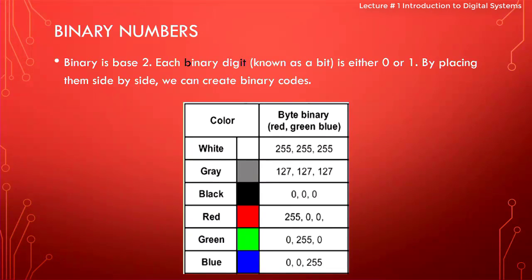Television sets, you see the resolution is improving. There are millions and millions of pixels on a screen. You can actually generate those pixels by digital logic, okay? And in most TVs, it is actually created using a certain bit number system for red, green, and blue. These are the primary colors, right? So this is the 8-bit system. For an 8-bit system, you can go from 0 to 255. And if all 8 bits for red, green, and blue are set to 255, it's going to create white color, okay?